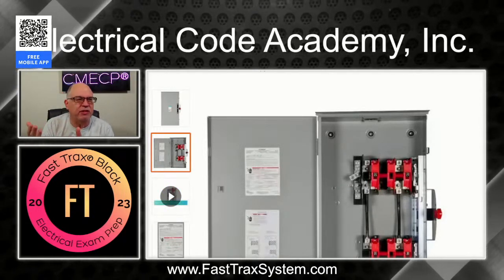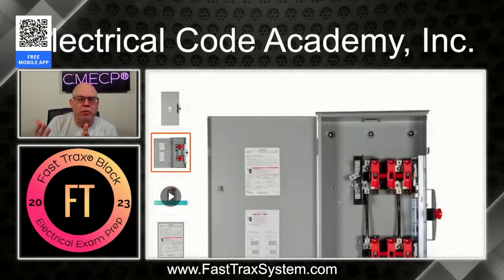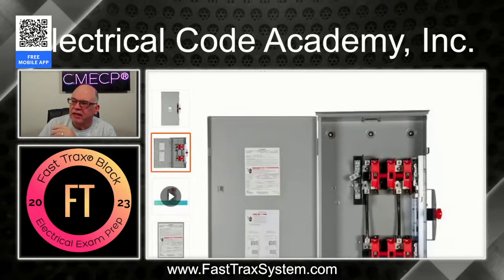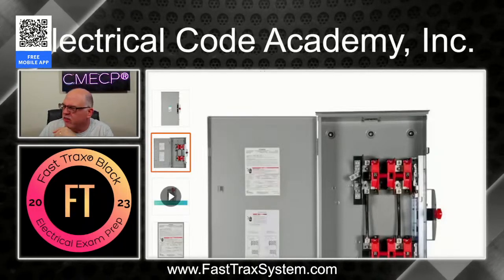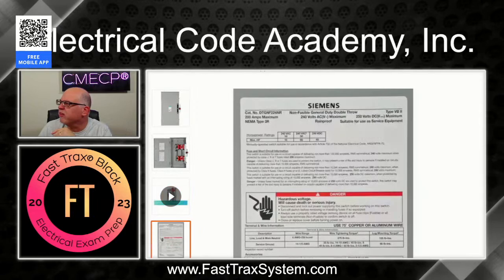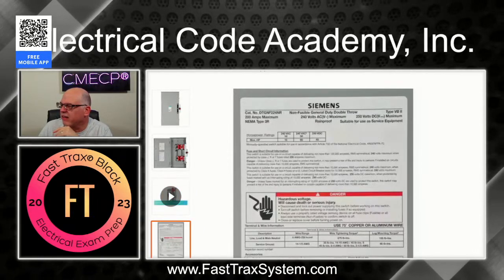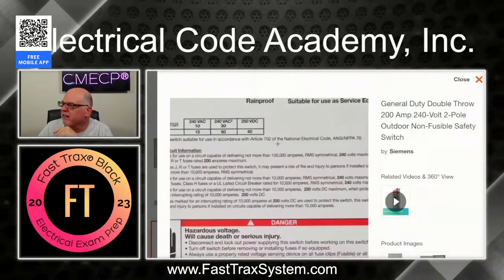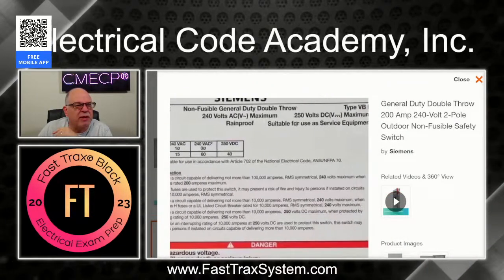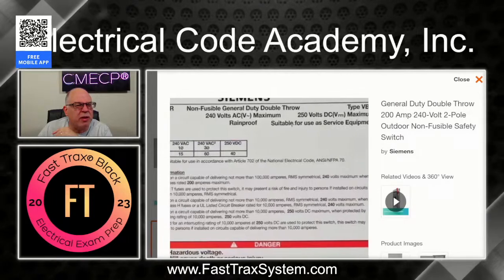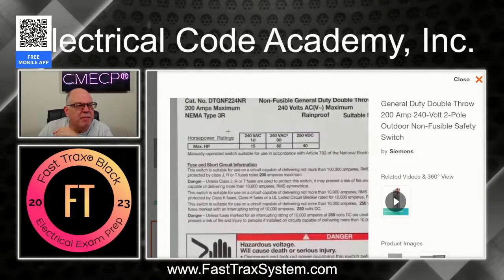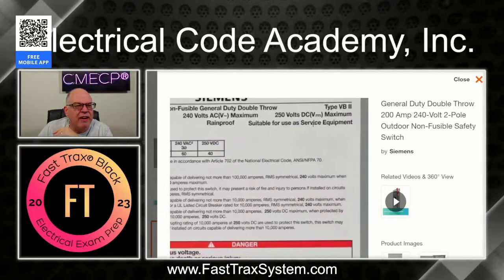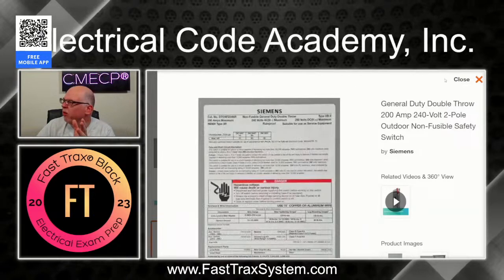It's a safety switch. It's non-fusible. It's listed. And remember what we said? So here it is, the label on it. Notice, look at the top. And I will try to make sure I can get over here so you can see it. Where my mouse is, right here. Let's look at it right here. See what it says right here? Suitable for use as service equipment, right? Right there.